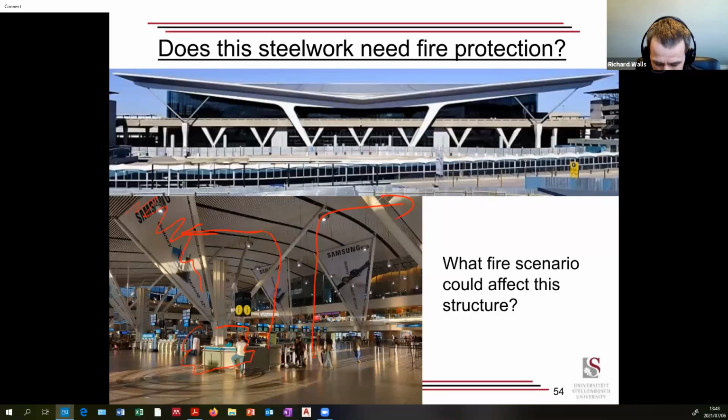So I was introducing fire scenario. Is it a localized fire, post flashover fire, standard fire, etc.? And heat transfer, how hot is my steel, concrete, timber? I've skipped entire steps. It's possible to do in a spreadsheet: how hot is a beam, a column, a slab, etc., and run the calcs quite easily and then get to a capacity. It's the same thing as you'd normally do for column design with just a little heat transfer going in the background.